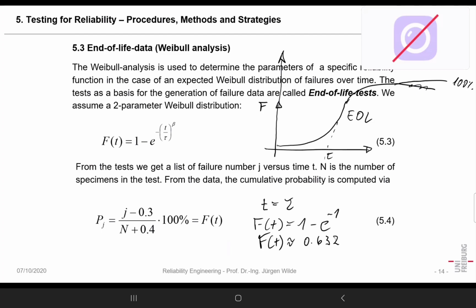That's on the probability axis, but on the time axis, you can say, as a rule of thumb, the mean time to failure or the mean cycles to failure is roughly 10% lower than Weibull. In fact, you can compute it more precisely based on the gamma function, but I think we will come to that later on.